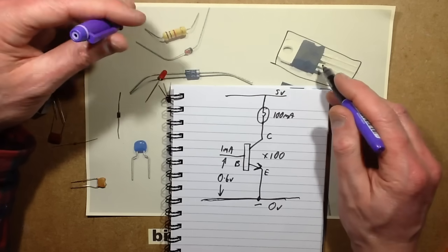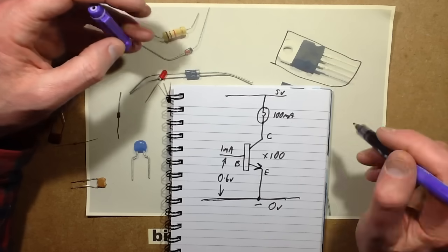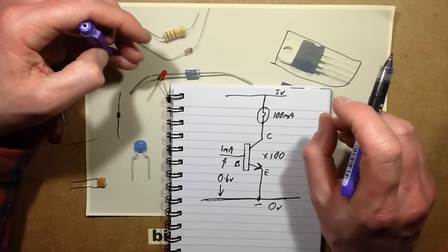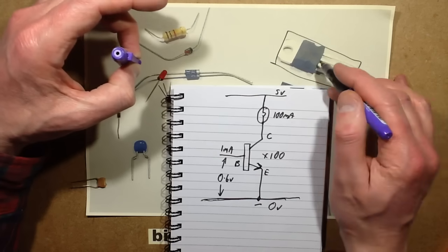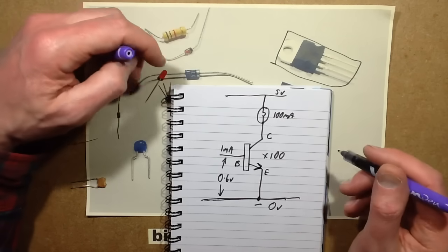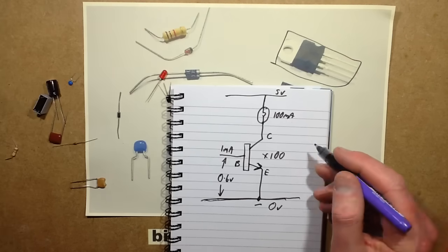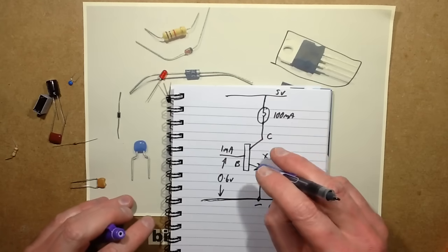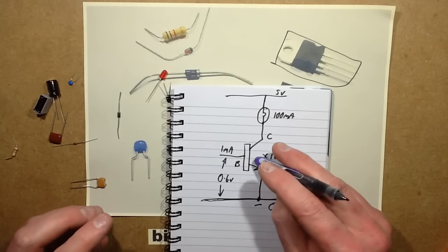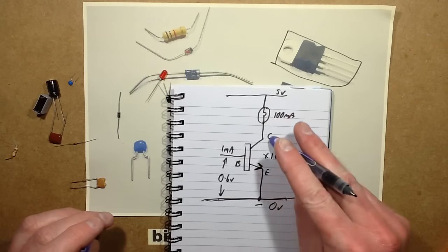They also have an extremely sensitive input, but they generally require a much higher voltage on their gate, as they call it, to actually turn on. But the current flow required to turn these on is virtually zero. It's a sort of capacitive effect. They're quite amazing things. You also get a hybrid. The MOSFETs are not as robust as the traditional, let's see, bipolar transistor like this one.